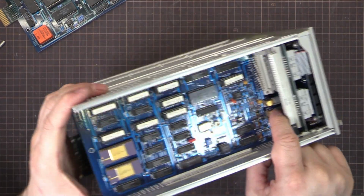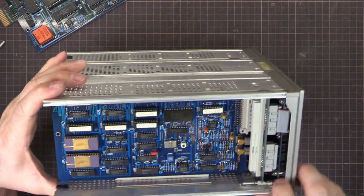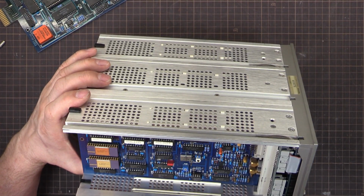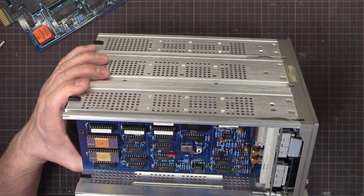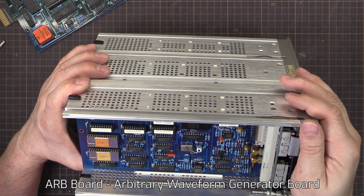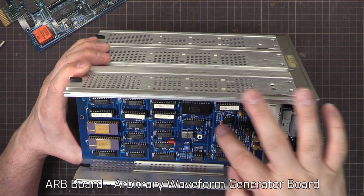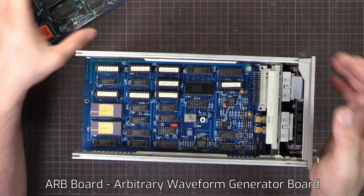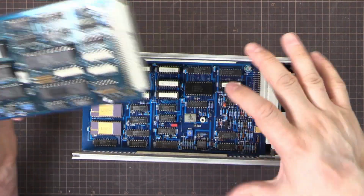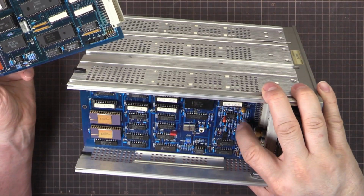We've got the connectors coming out here. So that's probably doing some sort of signal generator stuff. I'm not sure what this board actually does. I'll probably just put it on the screen somewhere here. And yeah, we've got 1 electrolytic there, a few tantalums, but we'll test all those tantalums. Unless they're actually causing a problem, we won't need to replace them, and they don't look like they've overheated.